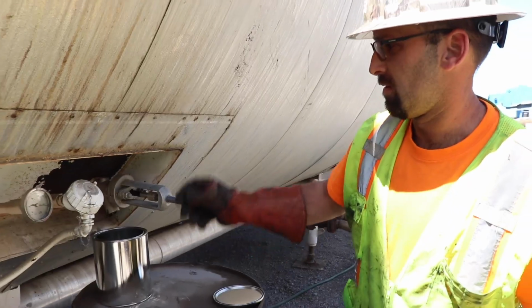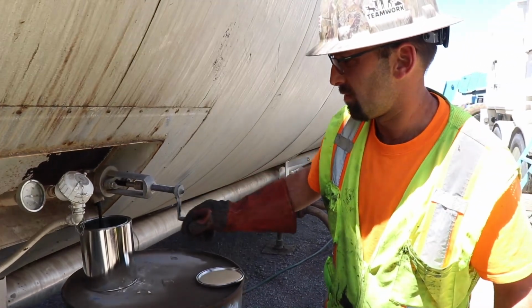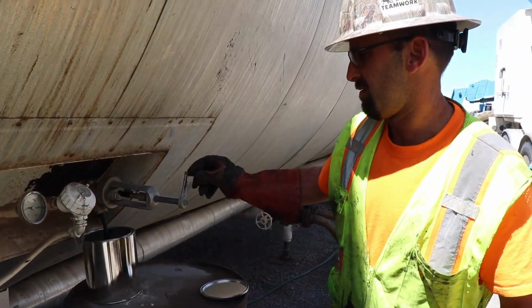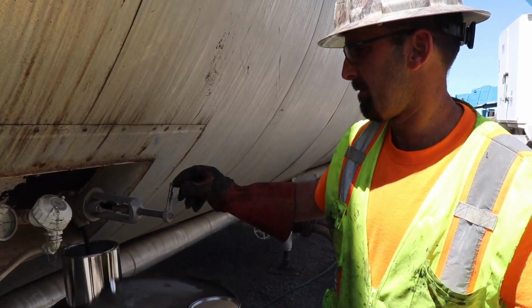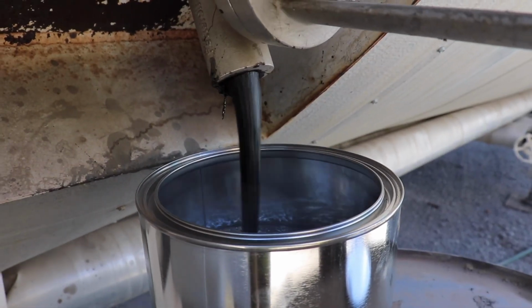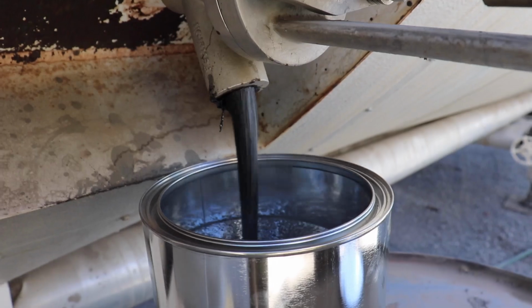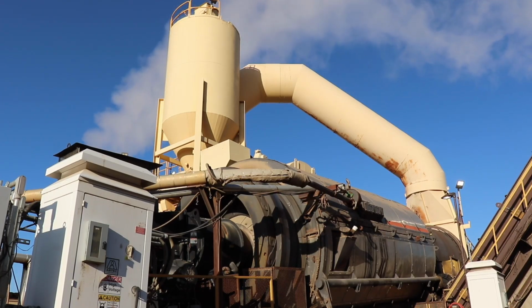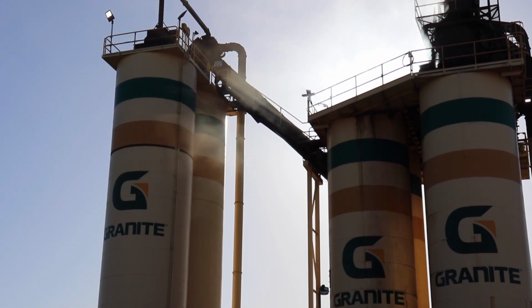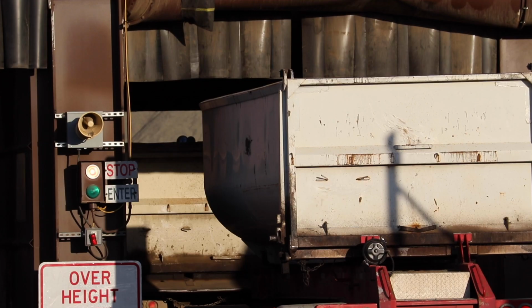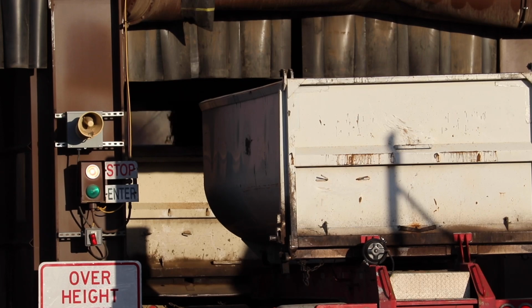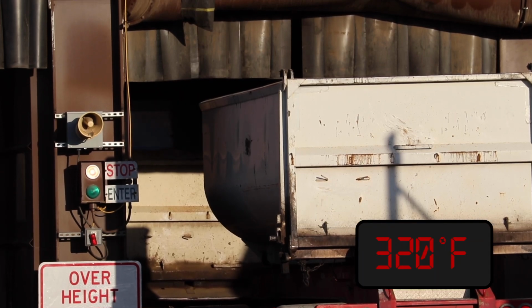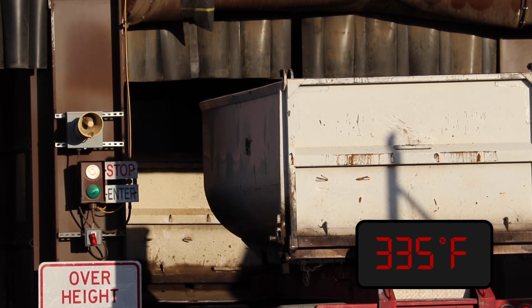At least one viscosity test is required to establish compliance for each asphalt rubber batch and holdover load. Measurement is determined by a rotational viscometer and presented in centipoise. The RAC binder and aggregate are now combined using conventional HMA processes. The RAC mix produced is now stored in silos, ready for delivery to the job site in trucks. Temperature of the material at this point should range from 320 to 335 degrees Fahrenheit.